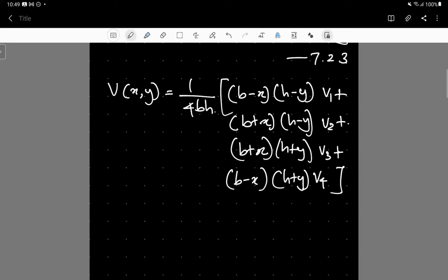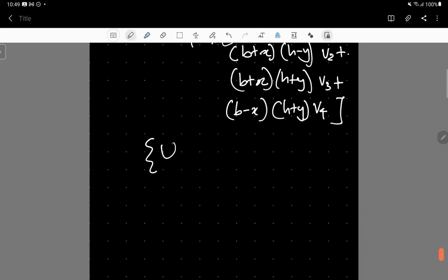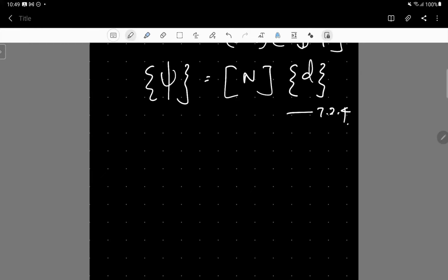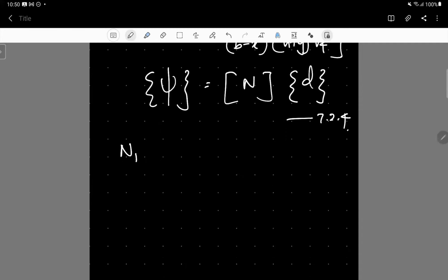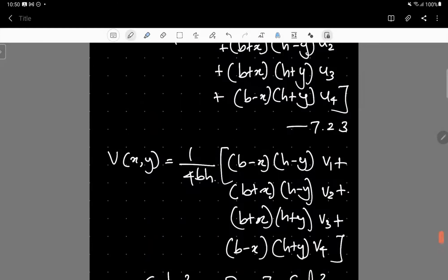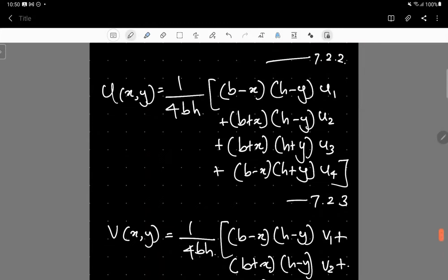We can now express these equivalently in terms of the shape functions, because we can separate the variables in these displacement expressions and express them in a more convenient way. If you separate the u's, you would end up getting these functions as the corresponding shape functions.